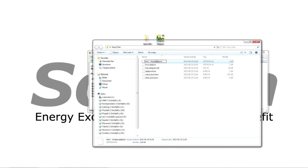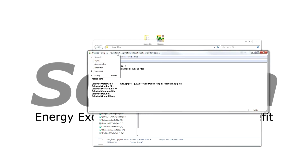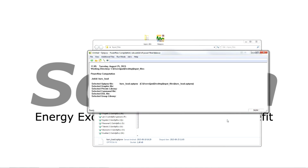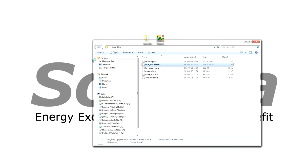Now we'll start with Task 3 in the OPTPOW exercise. First, we'll make a copy of curse.optpow and rename it as curse_load.optpow. We go back to the SIMPOW menu and select the newly created input file. We run and solve the PowerFlow computation.